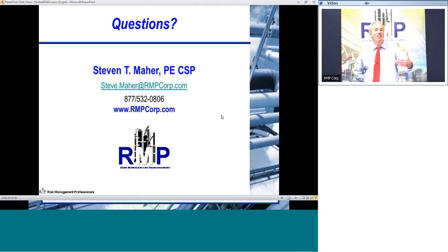Anticipate what you're going to be doing with a HAZOP study, so that you expect to jump around, address things as they come up, and meet the needs of your design team by working in one node one minute and then shifting as necessary to another node, and even bouncing around a little bit. Make sure you're structured so you can do that effectively.